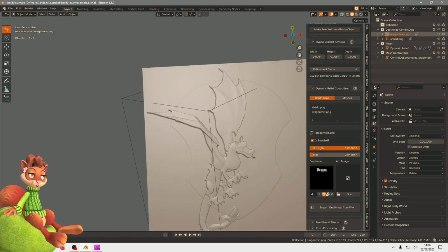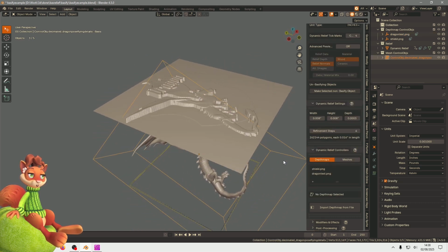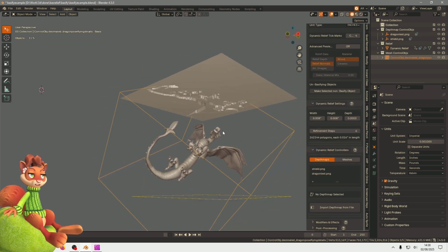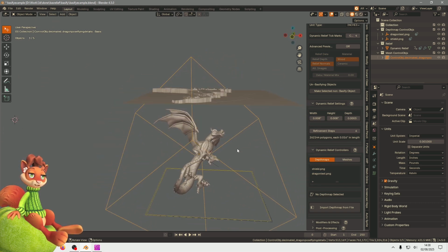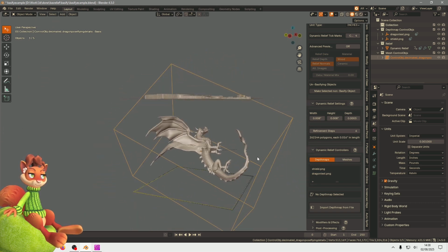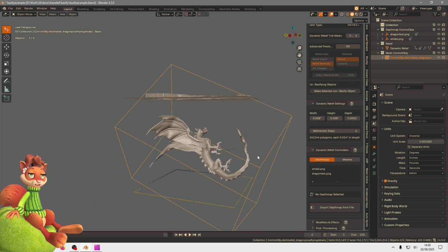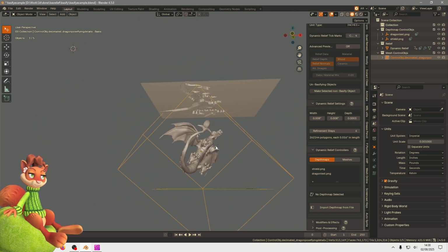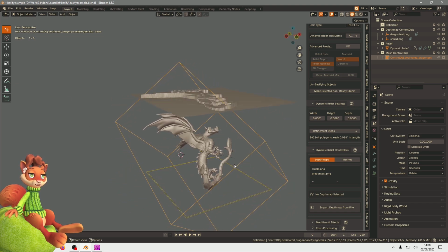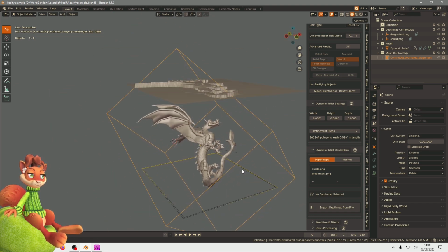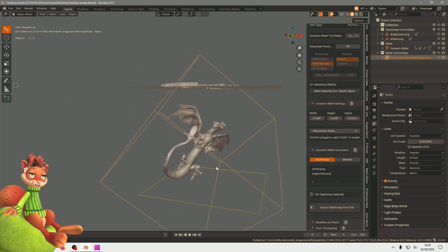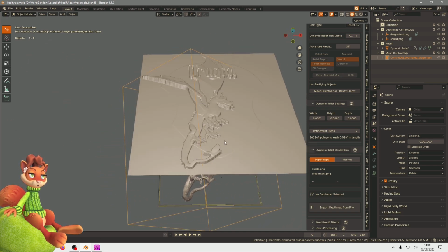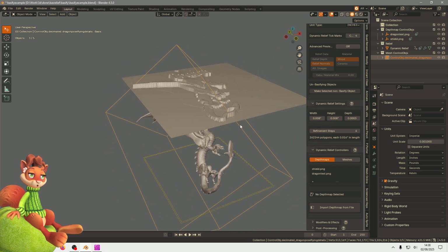You can set the bias of different depth maps individually, so you could have elements that go under or elements that go on top. The thing I did notice after I added depth maps as well as 3D objects was that the pink box disappears from the object and the grey box has disappeared as well. I don't know whether this is a bug, but that's something to bear in mind. It might be best to position your 3D models before you add depth maps.